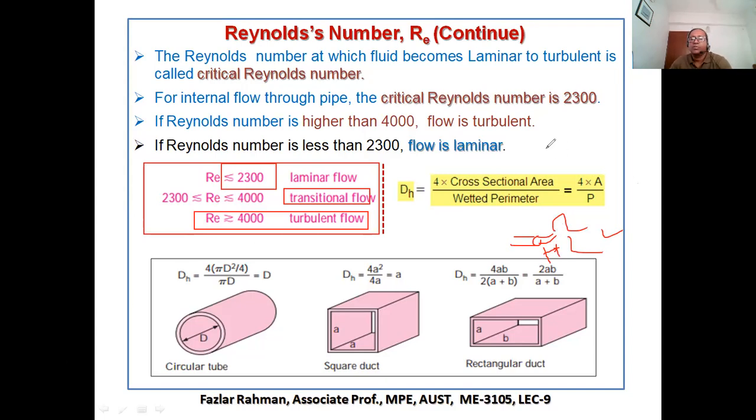And if you see somebody smoking, you see smoke coming out clearly in this portion, and some portions still go in a straight line, but all the smoke is kind of rotating. Then you'll see they are rotating more and spreading in both upward and downward directions. So this portion is called transition from laminar to turbulent, and this portion is laminar flow.